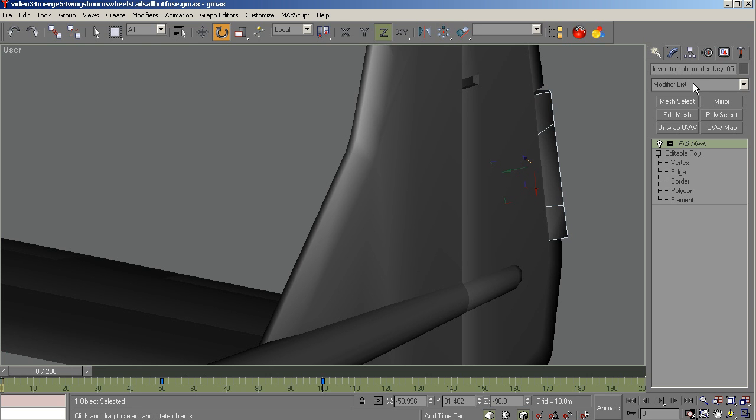And when you go looking at the SDK and trying to figure out what to use to animate these trim tabs, it's kind of confusing because the things that you think they are, aren't. If you use the straight trim tab, the thing will rotate around 4, 5, 6 times as you're rotating your rudder trim. So that doesn't work. But I discovered over time that the lever trim tab rudder key is the one that you can use.